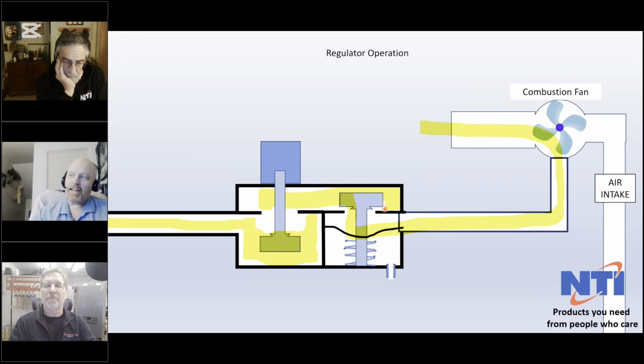The other thing that will happen in this scenario is as we speed the fan up, we're also getting a higher negative pressure or suction in the intake pipe, which is actually going to regulate the flow downwards. And the reason we do that is if you have 5 feet of venting, you're going to have a lot less suction pressure here than you would if you have 150 feet of venting. So the difference between those two can be as much as 7-8% of the boiler's output.